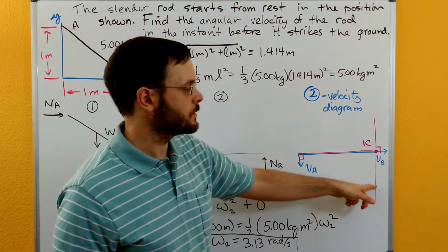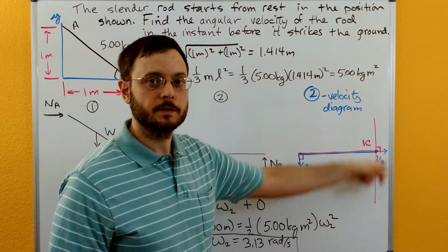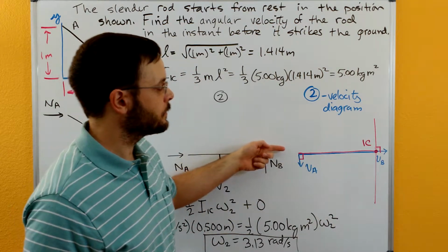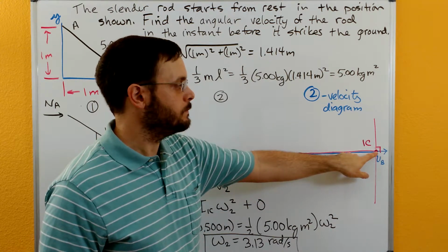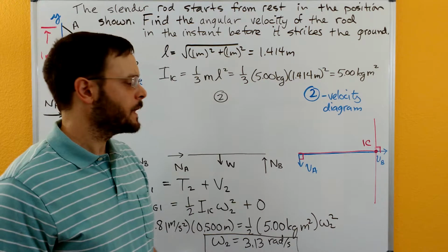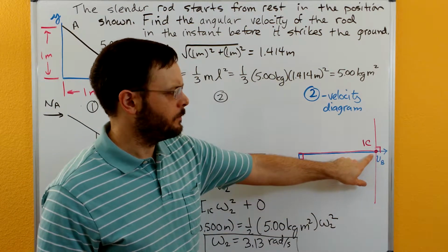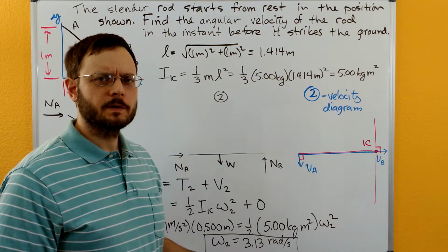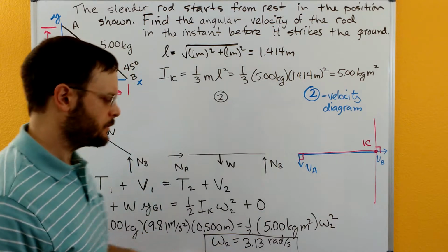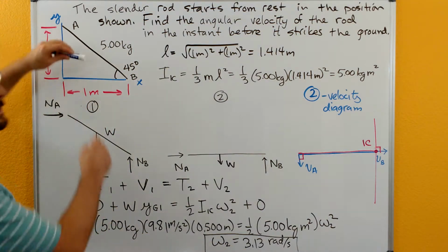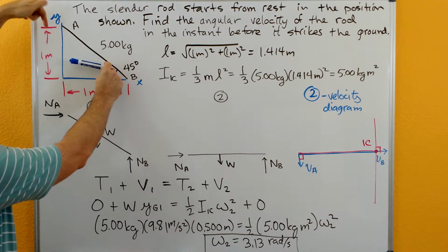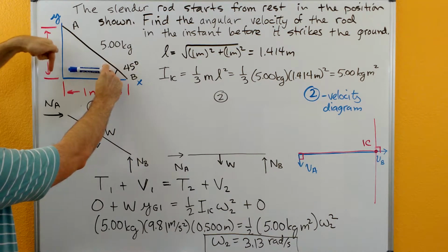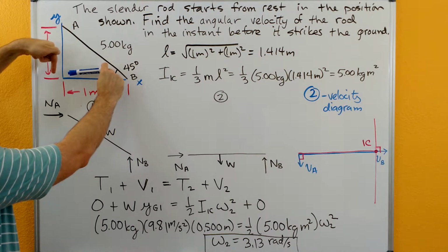And so we construct a perpendicular here to VB, that's this red line, and then we construct a perpendicular to VA, that's this red line. Where the two red lines meet is our instantaneous center. So strangely enough, at B, the velocity at B winds up being 0 in that second. So if you think about this kind of motion, it's starting here and it's falling. A is moving, but B is temporarily stopped here as it's going.